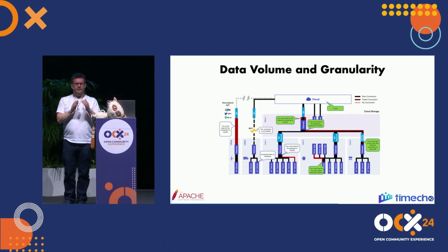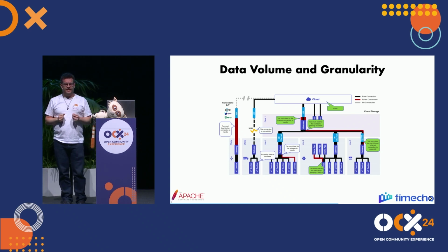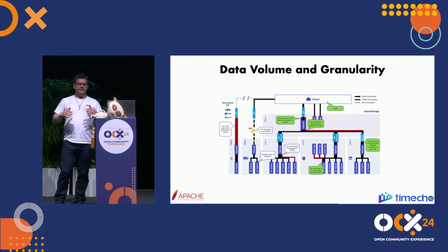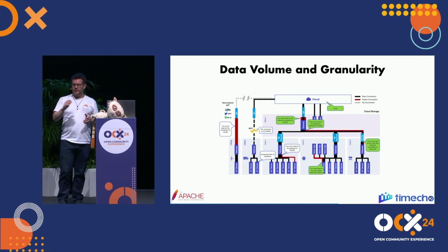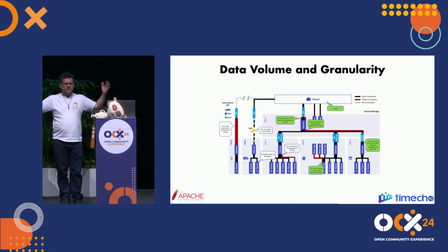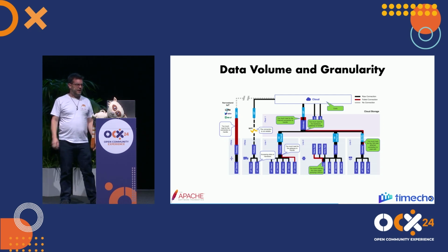If we're doing a lot of data collection there in order to make decisions on the gateway, usually all data being collected on the line level is replicated to the next higher level, even if it's not really needed. So you very easily overload the network infrastructure between the line and the factory level. It's like a tsunami of data coming up.